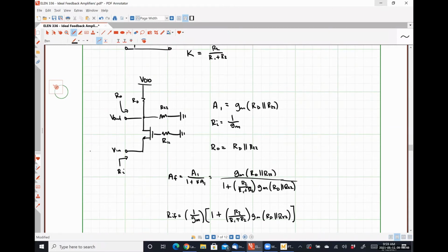Evan, what's up? So would the MOSFET be the mixer or the open? Both. It is both the feed forward network and it is also responsible for mixing the signal, because the current flowing through this guy, which is what the output voltage is dependent on, depends on VGS, where VGS is the mixing of our true input signal and our feedback signal. They do not in any way, shape, or form have to be two separate things, but they actually usually come out to be the same thing.